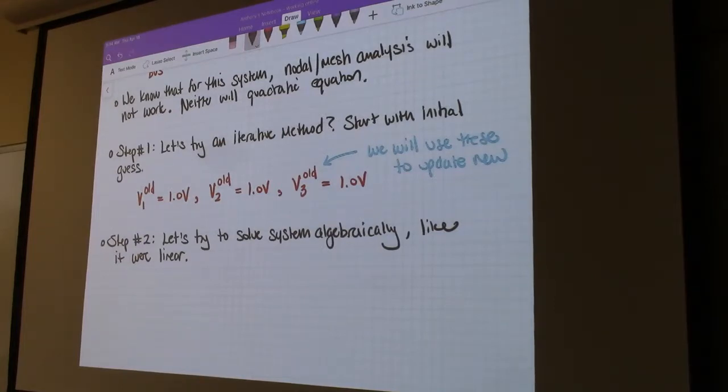The thing that was preventing us from doing that was the fact that we couldn't represent the buses, right, as voltage sources. Now, with this initial guess, we can. And so we can treat this, along with that assumption, like it's linear in nature.